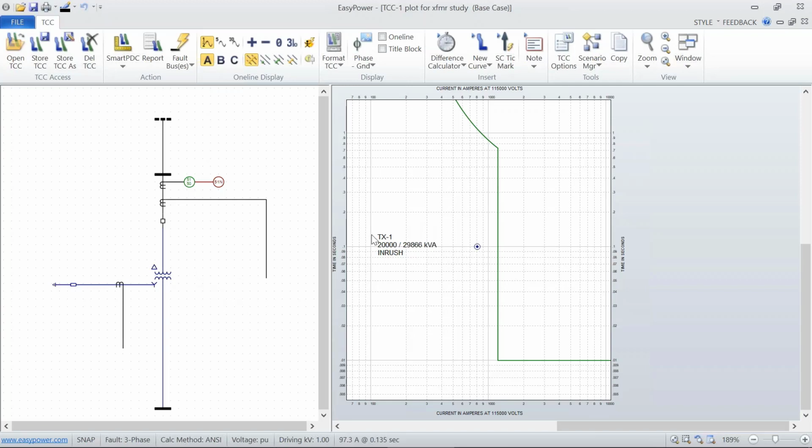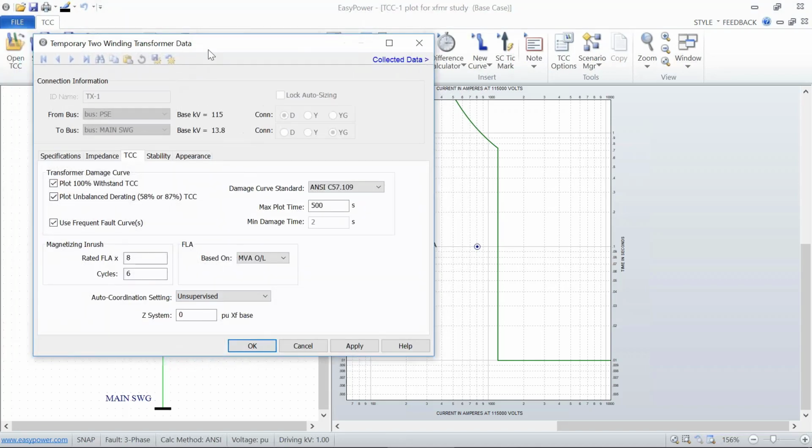Now, the one thing we've kind of rushed by is the fact that this relay on the primary side is sensitive to inrush current that could be harmonic rich and cause a lot of problems with relay settings. And that all goes to what's been used for setup of the transformer.